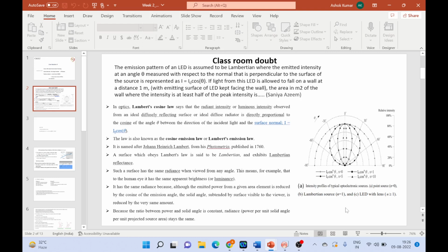I also wanted to show a typical LED. This emits at 780 nanometer, and some epoxy has been used on the LED. The LED part is just the middle part of it, and it is very small. You can see typical values, for example, full width at half maximum is given as 13 nanometers.